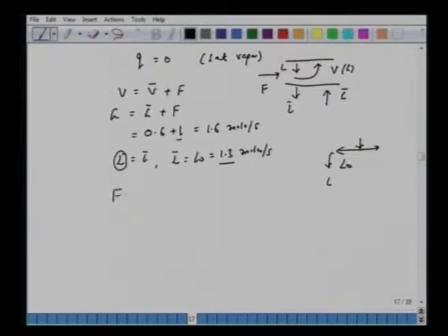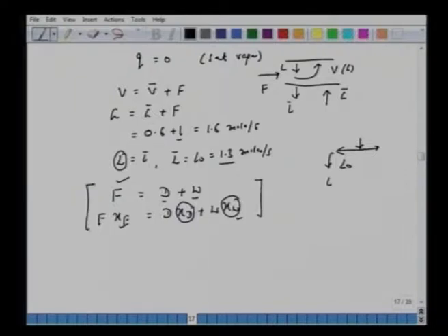We have the overall balance F equals D plus W. F is known, but D is not given, and W is not given. For the species balance, we can write F times XF equals D XD plus W XW. Again here XD and XW, the compositions of the distillate and the bottom products, are not given. XF is of course given here. So it looks like from these two equations we are unable to determine the rest of the quantities.